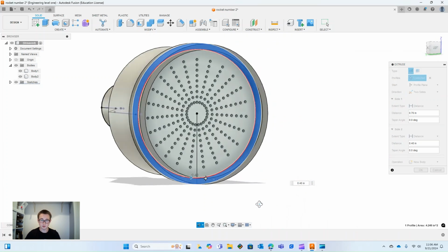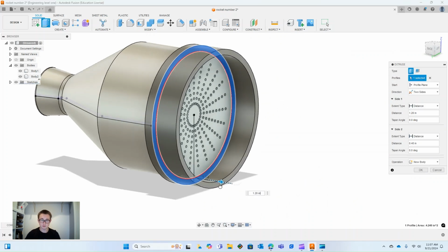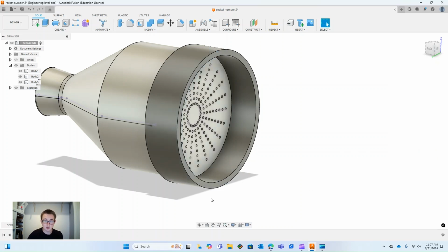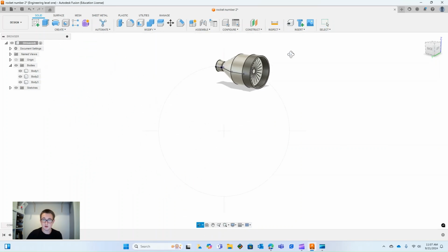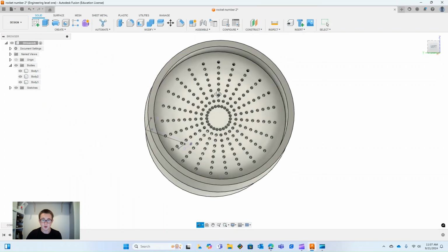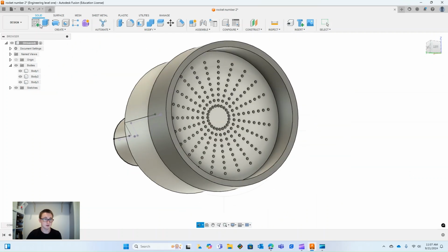And we'll need to move this out more. We'll do just 1.25 inches. Okay, hit done. And I noticed something while I was designing this right now, that this can just slide down, so we got to make a little bump there. So let's do that too.